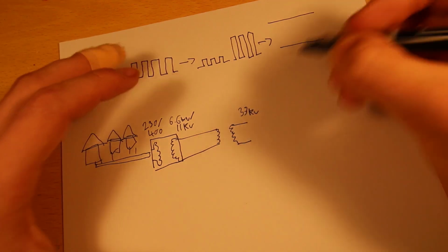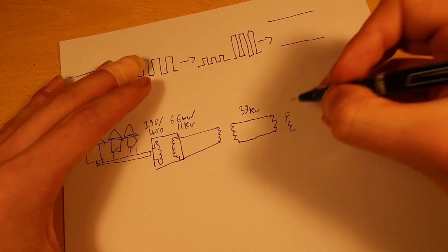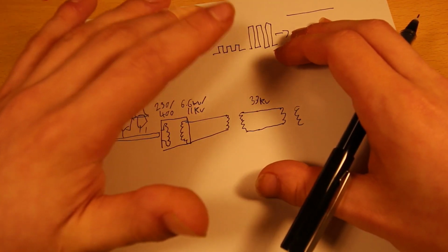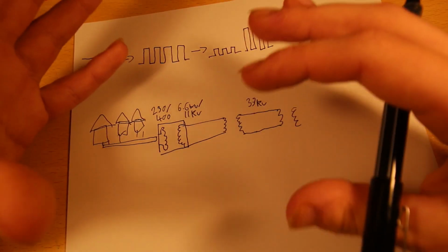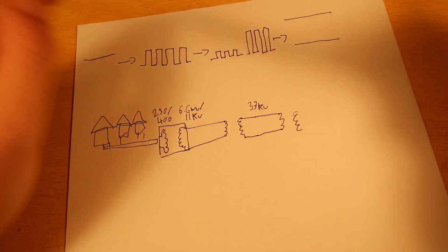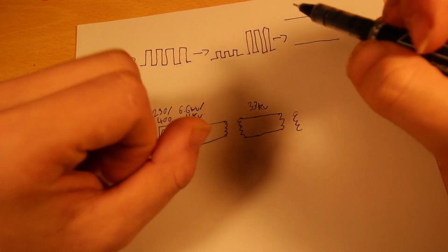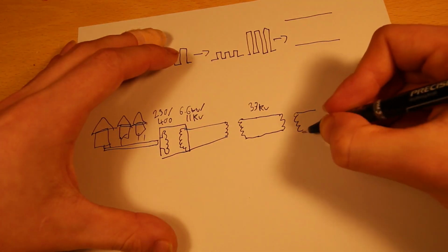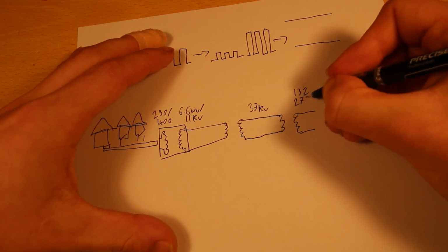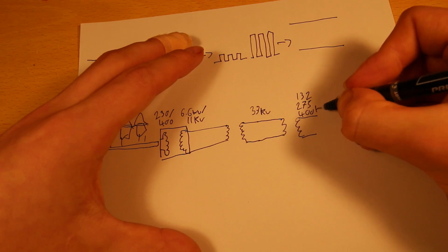They use 33 kV. That is then fed from another substation, which will take voltage, usually 132,000, 275,000 or 400,000, depending on how big of an area you live in. For me, my 33 is fed from a 275 station, which is just outside of the town I live in, which is not normal. Usually it's further away than that, but I happen to live near a rather large power station. So it'll be like 132 or 275 or 400 kV, depending on the area you're in.